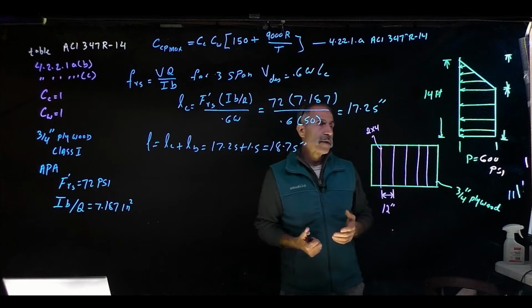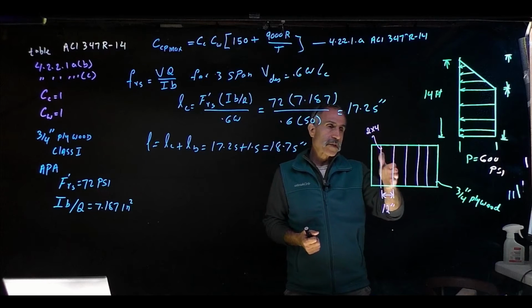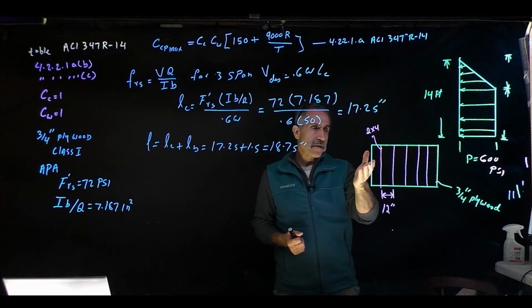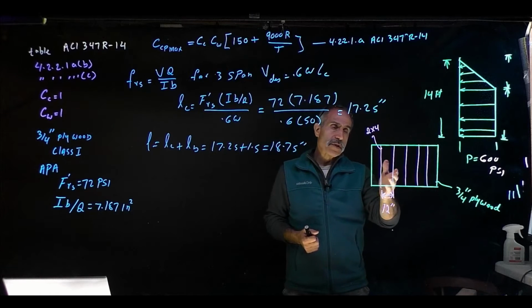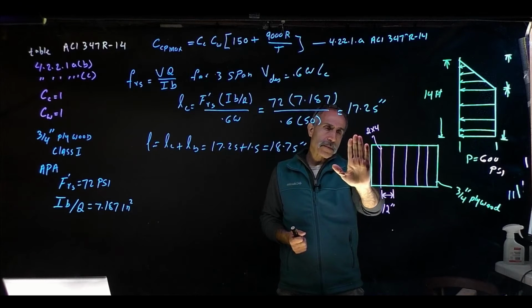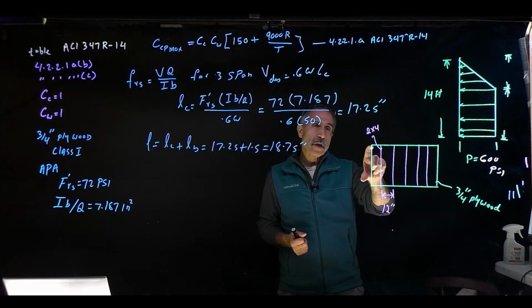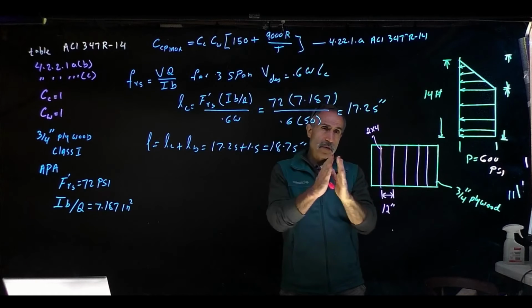You've got to remember, since we have a 1 foot spacing between the studs, and you have an 8 feet plywood sheet, the next piece of plywood sheet is going to come on this side. You're probably going to have 2x4 studs back to back with each other.